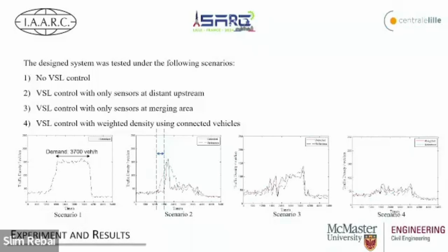So we tested four scenarios. The first scenario is without any VSL control. The second scenario is we have VSL control, but only with distant upstream sensors. The third one is with sensors at the merging area. And the fourth one is the one proposed in this study.